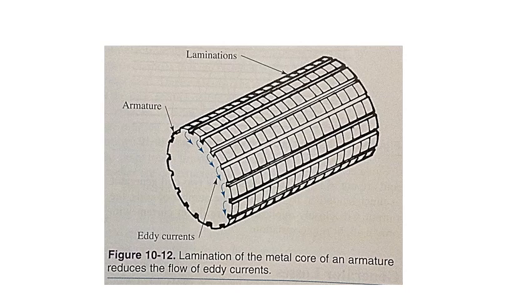These laminations reduce the voltage in the core and increase resistance to the power-draining eddy current. Eddy currents increase in the core as the speed of the rotation increases or the field density increases. When iron cores are used in rotating machines and transformers, they are laminated to reduce eddy current losses.